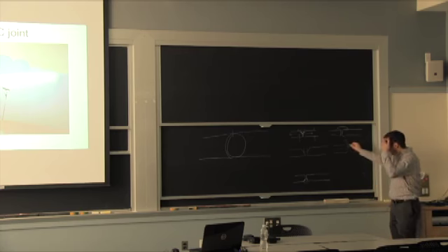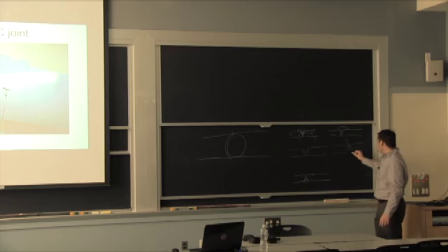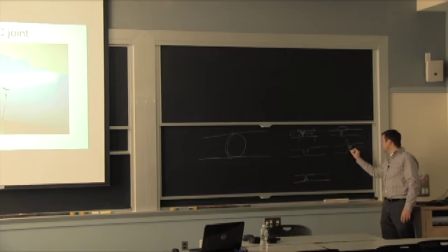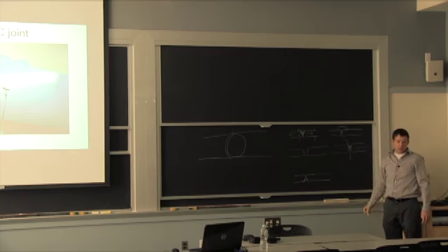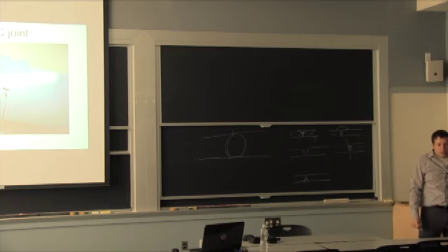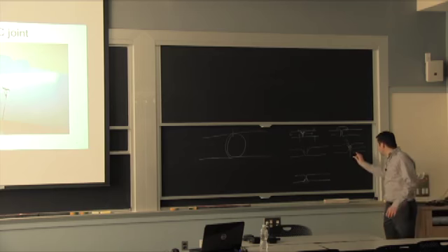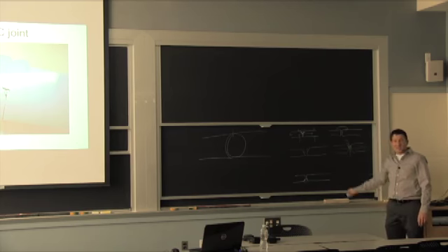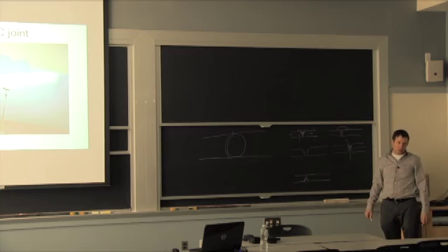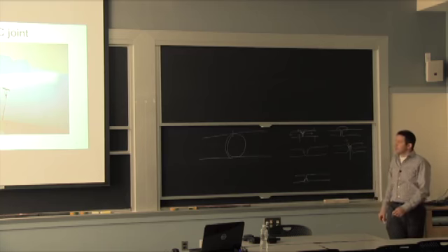The problem with this, if you bear with me, is when you do the root pass, because you can protect the top surface, say this is melted and it's filling the space, but you can't protect the back face easily, at least not with the same tool. There are ways that are used in pressure vessels where they circulate a shielding gas inside the pipe as well, to prevent the oxidation and degradation of the root. But in most cases, you'll have an issue there.